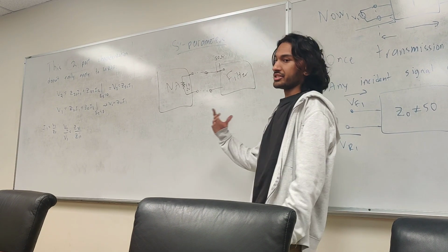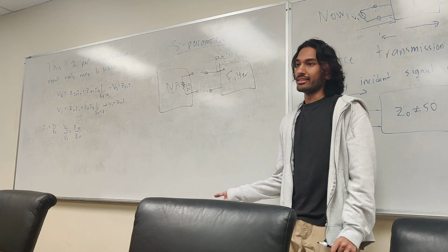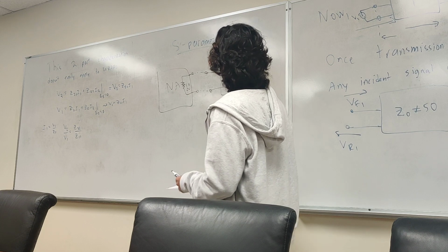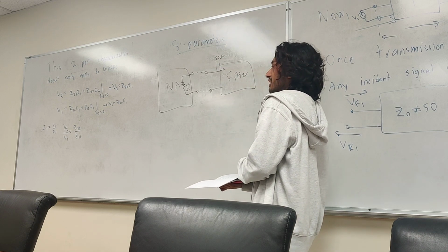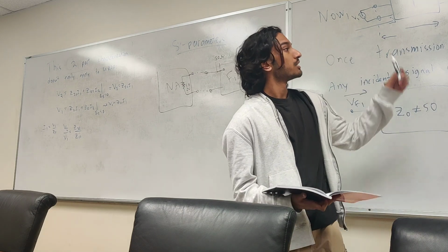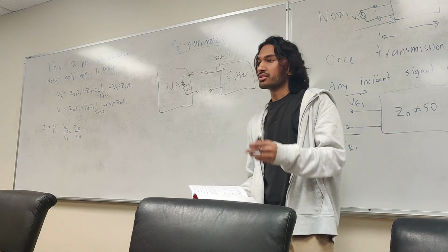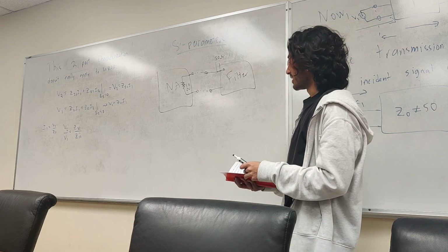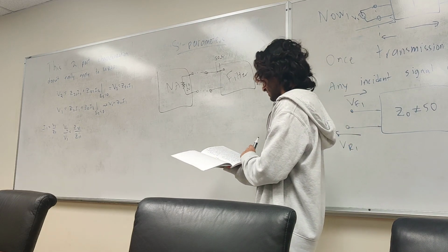This is not voltage dB. This is power dB. So that's one reason. When we typically talk about S parameters in terms of dB, it's referring to power. When we talk about them in linear, it refers to voltage. It's a bit of a weird notion. Normally you'd stick to one or the other, but that's typically how it is.